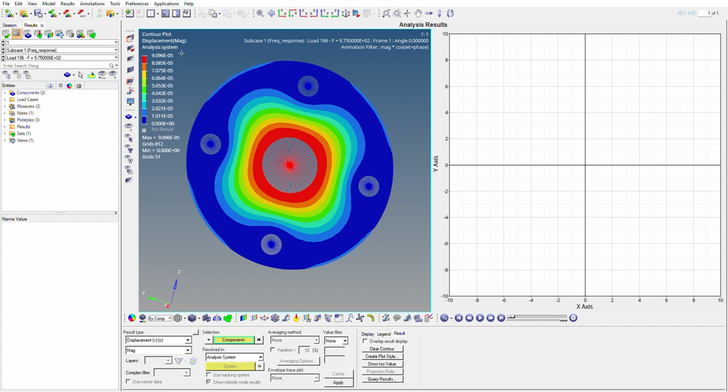So yeah, basically the maximum displacement is increasing with the increase in frequency to which the plate is subjected. Okay, so this is basically how the plate will behave when it's subjected to that frequency range. Right? Then we can also check the element stresses here.